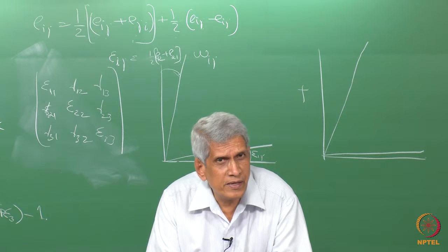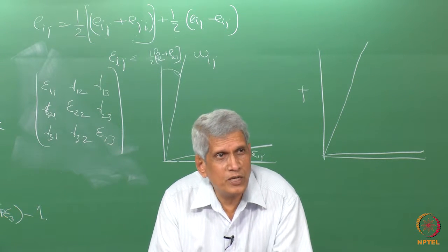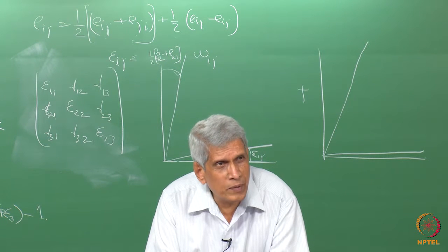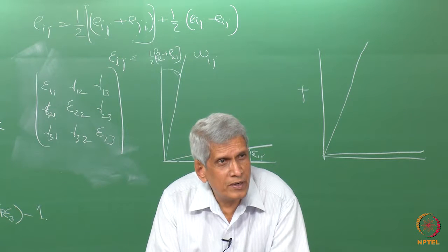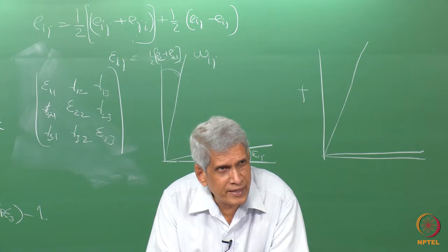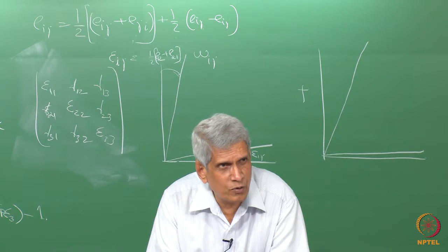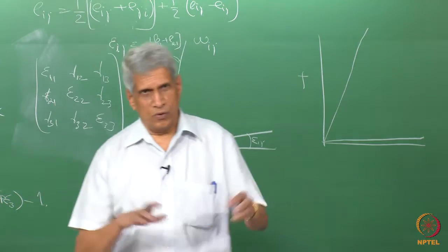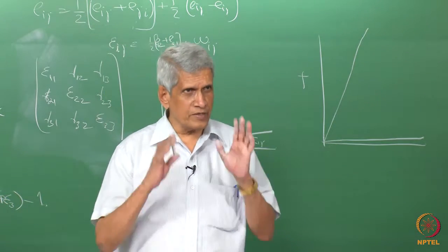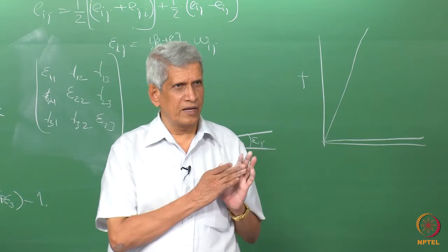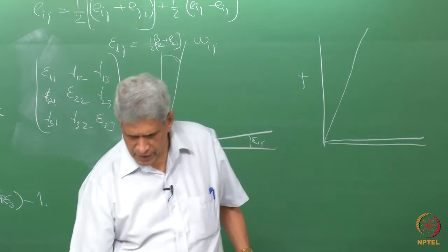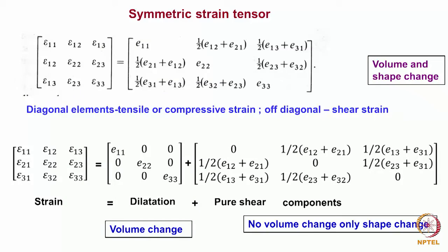That is because the shear is the part where this rotation part also comes. So a simple shear need not mean that an atom has undergone some deformation. It might have undergone some displacement, and the total displacement which it has undergone could be some due to pure shear plus some due to rotation. Okay. So considering it as a pure strain which the sample is undergoing, then it is going to be only the pure shear as well as the pure strain which the material undergoes. That is given by only this symmetric strain tensor. The other part of it is essentially the rotation part.